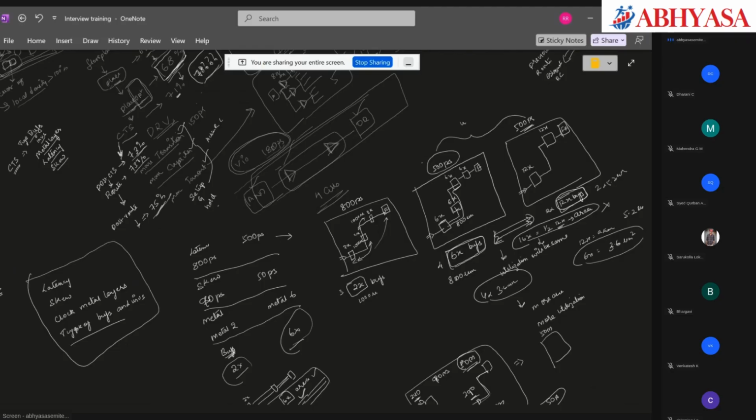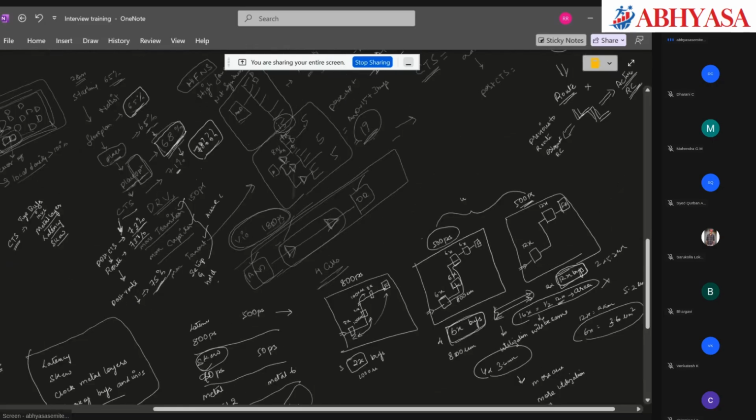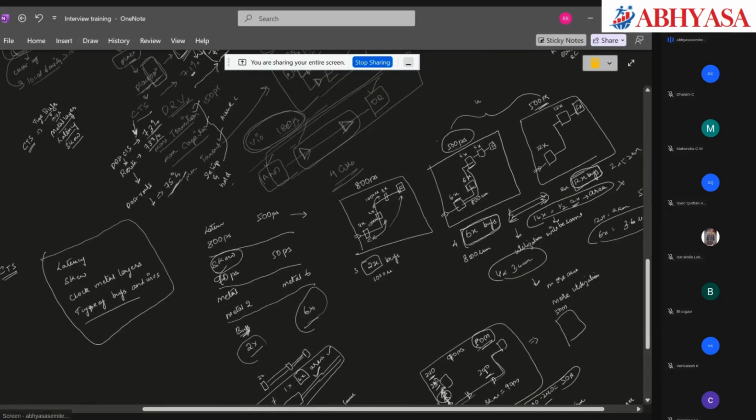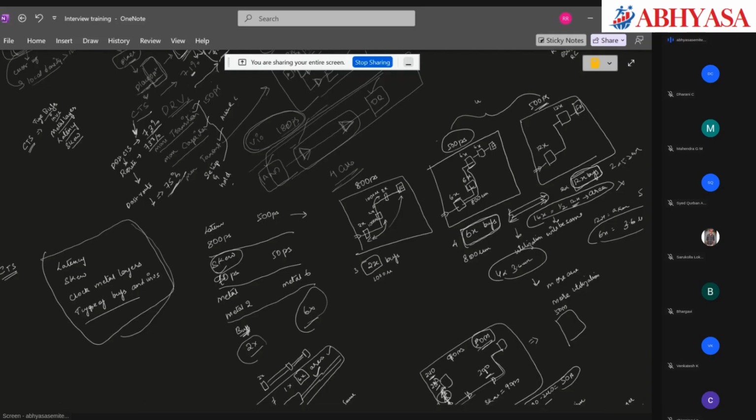Since sometimes our primary target will be skew and latency, because that will directly affect the timing. Sometimes we tend to use more area to balance the skew and all. If skew is not that of a problem, we should look at reducing our buffer count being added in the CTS, right? So this abnormal jump is due to improper values that we have given to build the CTS, and that is why the tool has added unwanted number of buffers in the design.